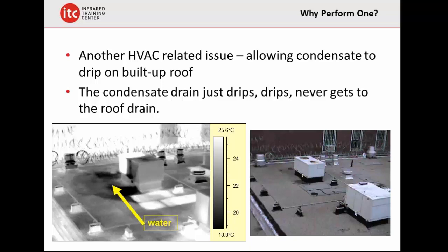It is highly dependent on sky conditions, and this is why when you come to training, we teach you all about the Stefan-Boltzmann law. We teach you a little bit about Planck's law. We teach you about radiation heat transfer. It's sigma T to the fourth, and that's the first integration of Planck's law. It's called the Stefan-Boltzmann law. You're radiating to a cold sky as a function of the fourth power of the absolute temperature.